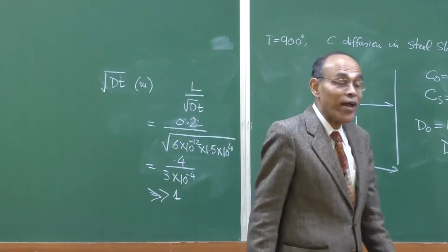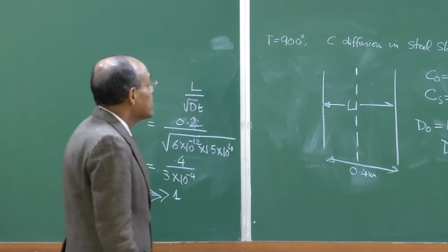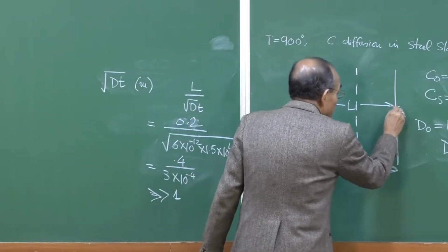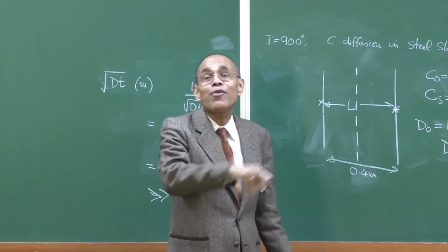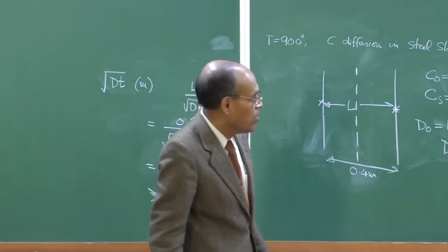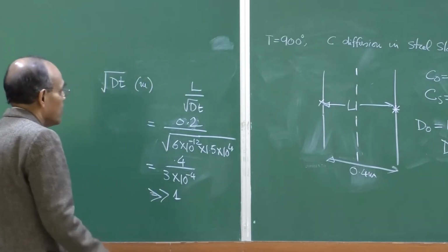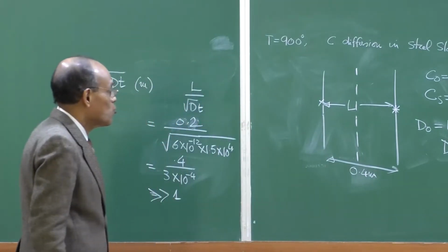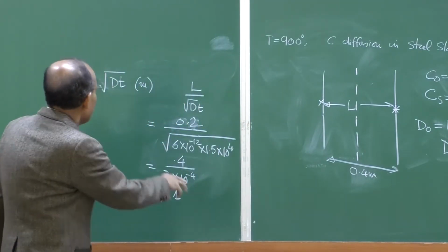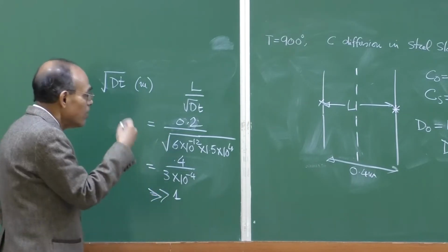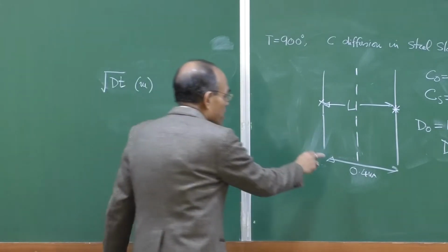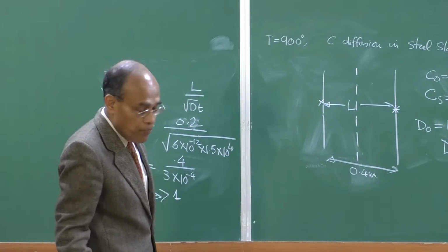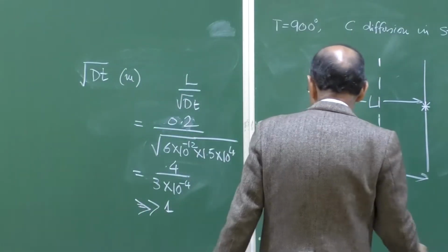the error function solution where we approximate the geometry to be a semi infinite geometry. It is also possible in this case to apply the infinite series solution, and you will see that the semi infinite geometry solution as well as the infinite solution will practically merge, illustrating essentially that from either of the standpoints you should be able to address this particular point. So, having done this, I would now like to consider this finite slab geometry as a semi infinite geometry and start solving those particular questions that I have written on the right hand side.